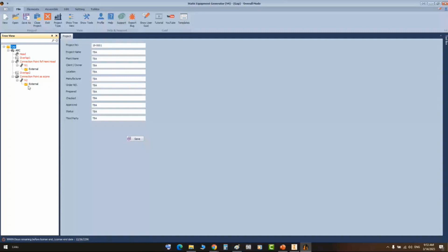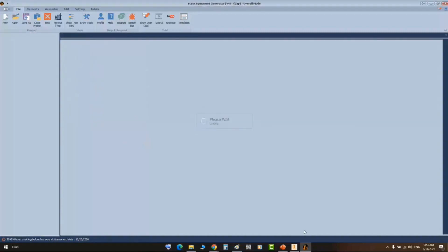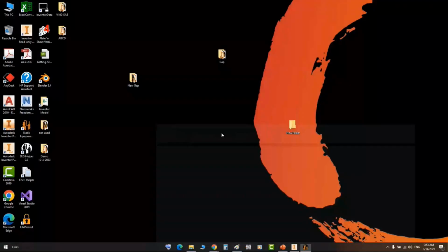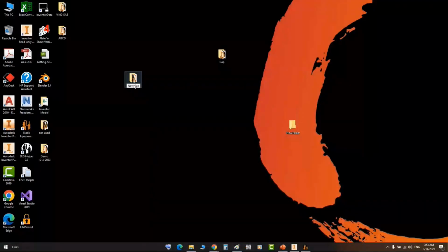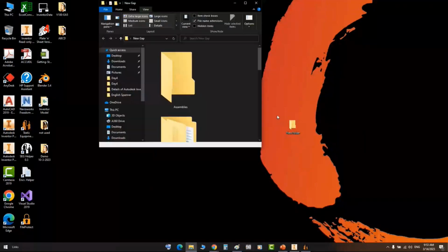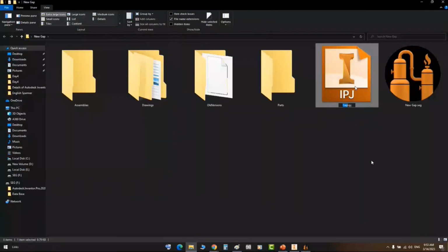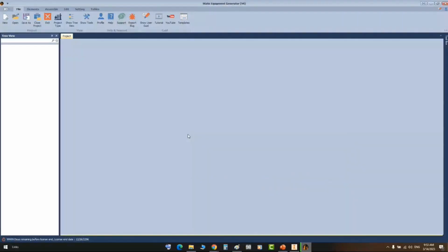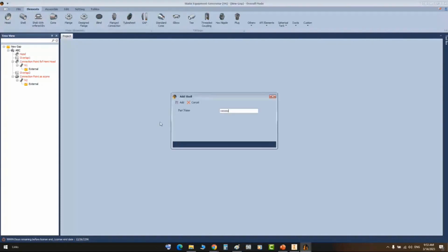Let's try another thing by renaming all parts, all nodes here inside this folder, like renaming the SEG file. So the naming here, you did it manually. So let's rename all related files manually. And when you try to open this project, like that one, and try to add a new element, you will get this message, which informs you that you will not be able to add new objects.